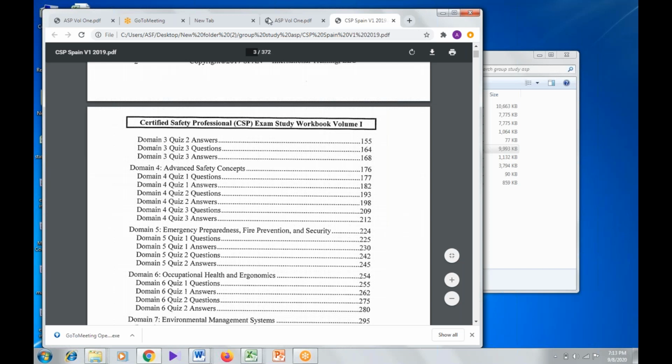If we are talking about the chlorine exposure threshold limits, the risk management plan RMP applies for sites where chlorine exceeds 2500 pounds in a single unit. So it means that if the chlorine exceeds 2500 pounds in a single unit, then the risk management plan RMP is activated, I think. One thing I wanted to add.